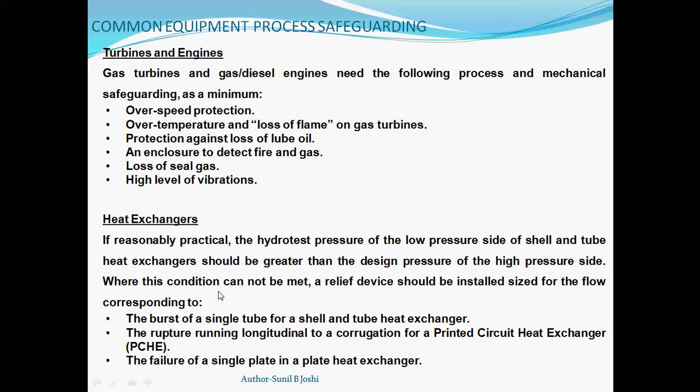But in general, if you go to API references, you will find the reference of the low pressure and high pressure sides, hydrotest pressure and design pressure that need to be compared, and then accordingly you have to reach the conclusion whether you have to apply the burst of a tube as one of the scenarios of relieving.